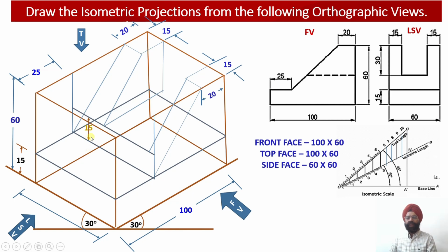Please see, now I am going to show the dimensions. From this top surface of the ring, draw a distance of 15 millimeter upwards, so that the thickness of this web in the side view happens to be 15 millimeter. This inclined surface will be having the larger length, but the vertical length I am bothered about. So the vertical length from this ring point should be 15 millimeter over here. So this way I need to evaluate the starting point of this U, and similarly this point will also be obtained. So by two methods I can obtain this point.